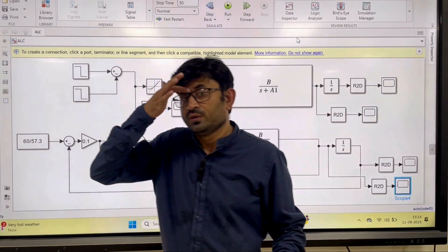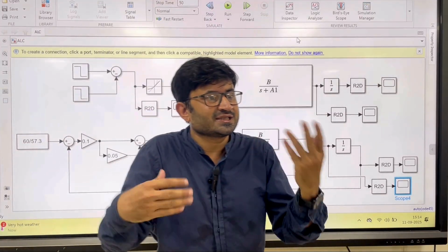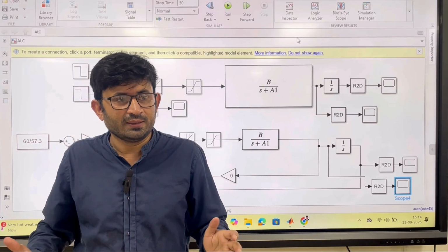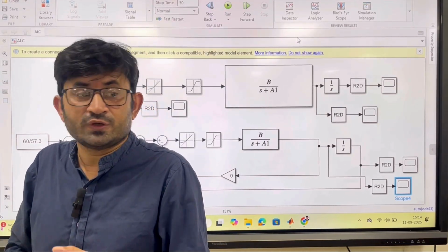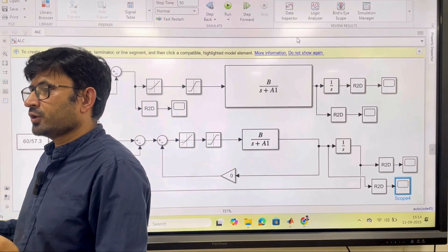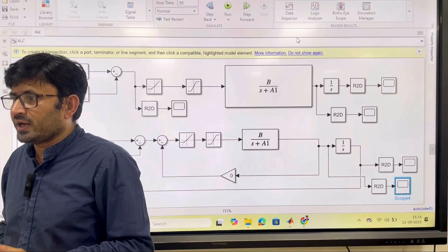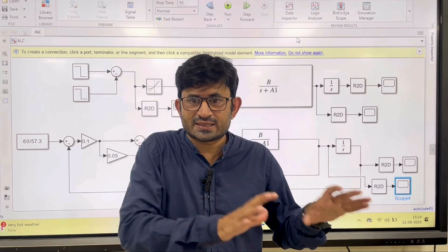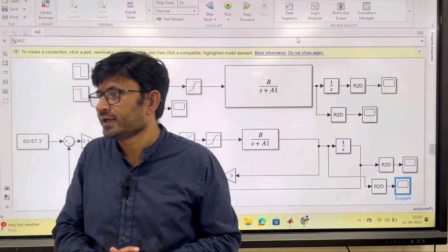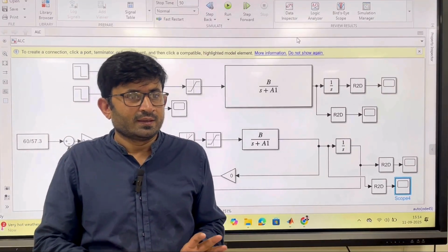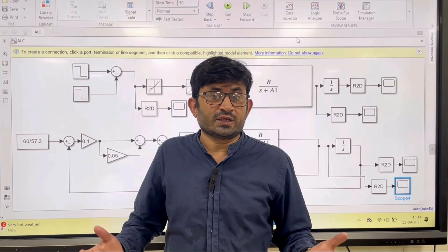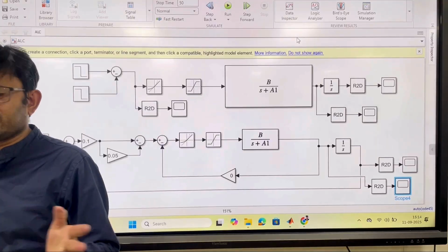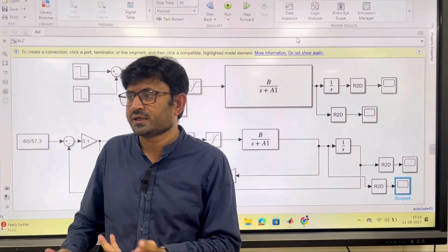Okay. Now go back to your home and change the CL delta A, change the CLP, and play with this code and enjoy. When you increase CL delta A, your aileron control power will increase, right? So actually, you can control while taking less time as compared to what you are controlling here. Okay, rate limit. Then you can take a powerful actuator, where the rate limit is more. So that kind of thing you can play with. Change the parameter again and just play.